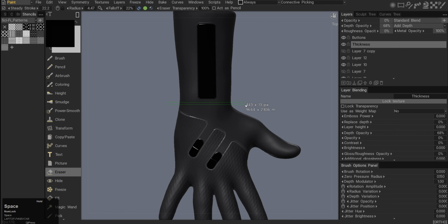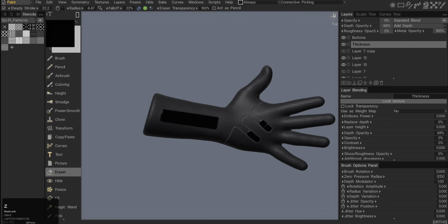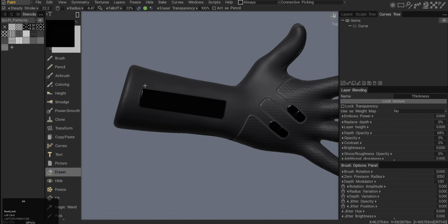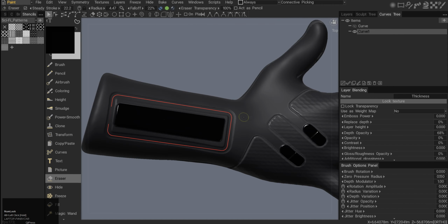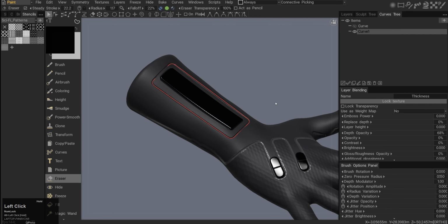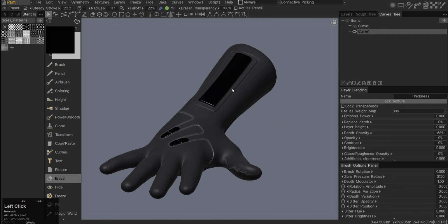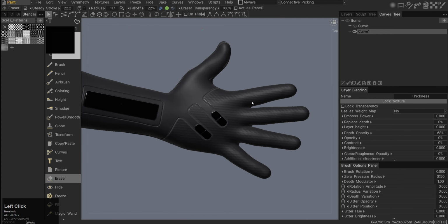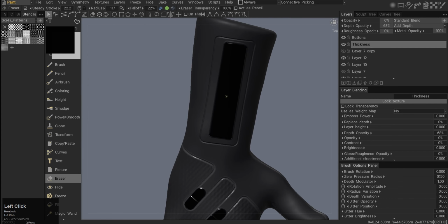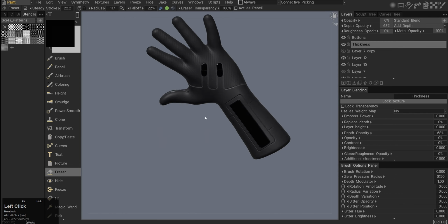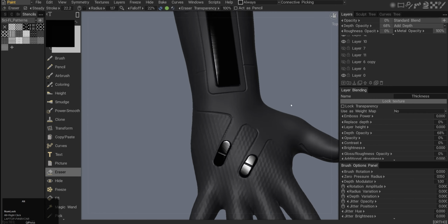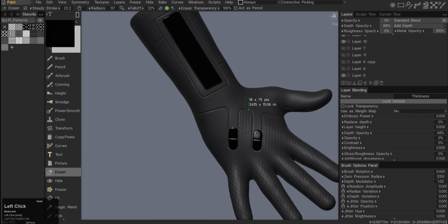And then I wanted to make some kind of a seam around that LCD screen, and I didn't try the rectangular tool, didn't like how it looked, so I decided to go with the curve tool again. So I'm just drawing the curve around, and then picking all those guys around and beveling them, and now making my brush smaller and doing the seam around the LCD screen. And I'm also doing some seam cuts, just using a rectangular tool and depth set, pressing Control and doing it at -11 essentially.